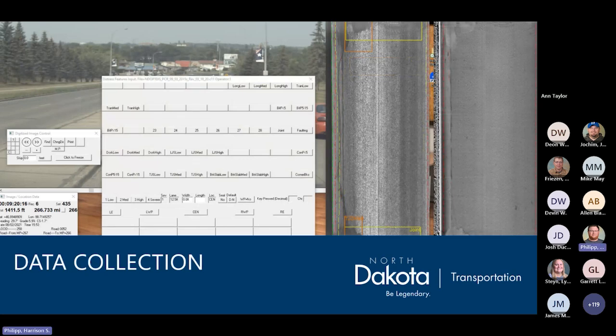This pop-up window is used for marking out spalls and cracks. You would run into a spall area, for instance this area, you would then click one of these 3 spall areas, and then you'd click and drag, and then it would capture the size and location of the spall. You would then have to go through and do this to the whole roadway.